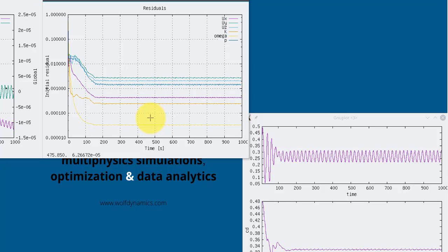One of the questions newcomers in CFD always ask is: I'm running steady simulations, why is my simulation not converging? Remember, steady doesn't exist in reality. It is kind of a trick that we use just to get fast outcomes. The fact that it's not converged is just an indication that your solution is in reality unsteady. We know this problem has those vortices at the back of the model, with some vortex shedding and detached flow. So in reality it is highly unsteady, and this steady solver will never converge.